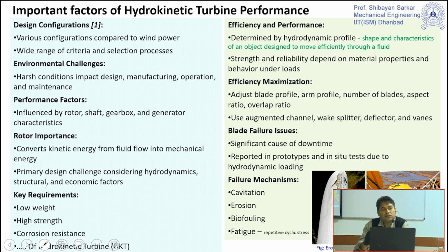Your design should be such that there is no sharp corner, and there are two aspects to this. One is the aerodynamic concept. Another is that a sharp edge may generate stress concentration, making it prone to breaking because of fatigue failure. These are the aspects you have to consider whenever you are selecting your material, as well as your design.